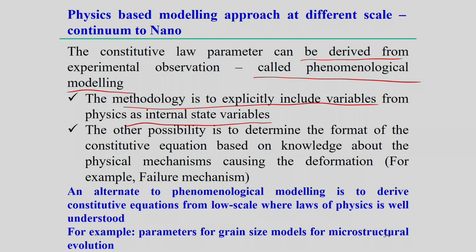Now, during the deformation process, how dislocation density evolves can be linked with the parameters in terms of the strain, the strain rate, or temperature. But the internal variable in this case is the dislocation density. Now, based on this dislocation density, considered as an internal variable during the recrystallization process, we can predict the average recrystallized grain size after the deformation process is finished, or at a particular state, the amount of stress generated through the recrystallization process.